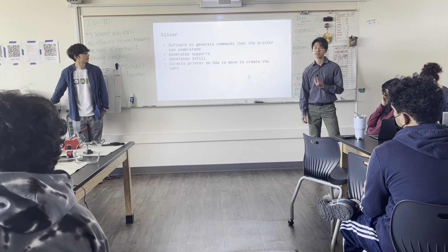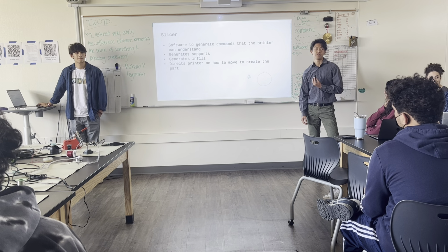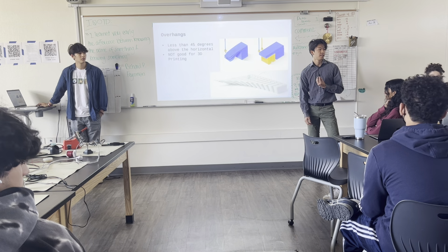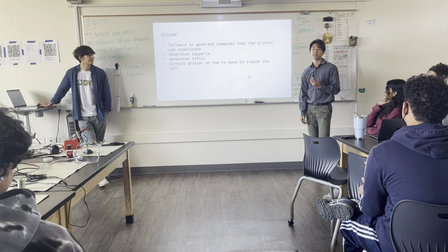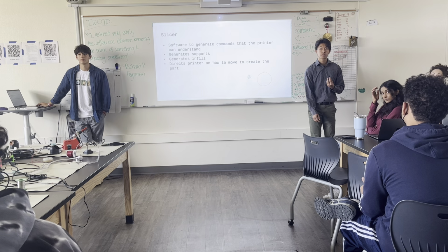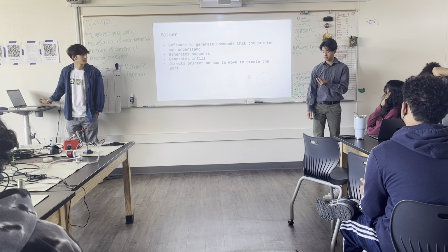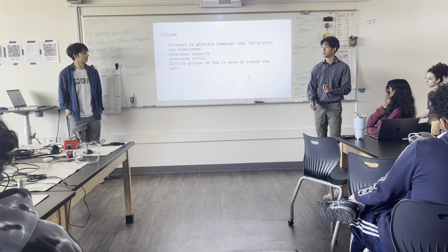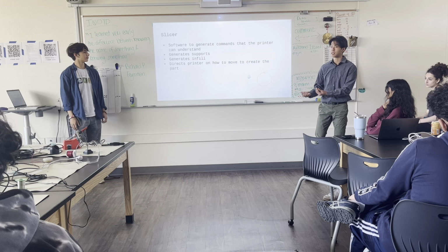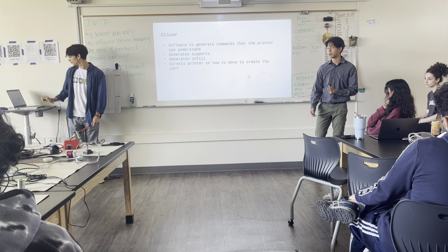Does anyone know what the slicer is? Heard of a slicer? Sure. That's right. Yeah. So the slicer basically turns your STL file or whatever file you put into the slicer into commands that the printer can understand, generates infill and supports, and directs the printer how to move.